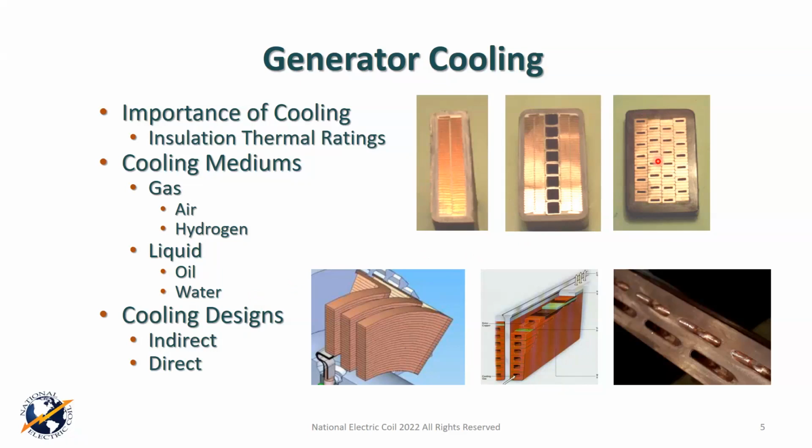Later, as things evolved, what they found out is they could put solid strands around the hollow strands. And by having solid strands, they had more copper, so they decreased the I-squared losses and they push more current and keep the temperature down, and made the machine much more efficient for the size. So this is a more recent version, and when you see ones that have all hollow, they're usually an older unit. Ones that have more and more solid strands around the hollow, well, those are probably newer vintages. So this gives you an idea a little bit about the cooling on the stator.